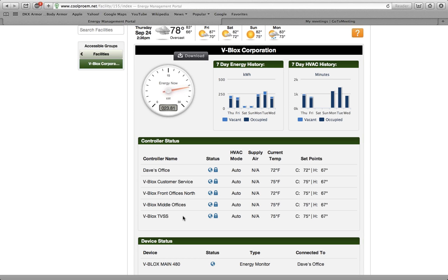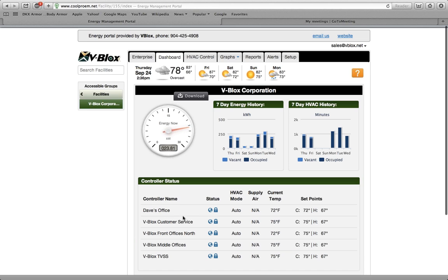One last thought when it comes to that, if your air conditioning is running 3 hours at night, we can't save you a full 3 hours because we're going to have to bring it on a little earlier in the morning, so when you walk in the door, it's nice and cool. So out of that 3 hours, we might have to bring it on an extra 20 minutes early. So instead of saving 3 hours of runtime, we save 2 hours and 40 minutes. But per day, and then on weekends, that can really add up to substantial savings.